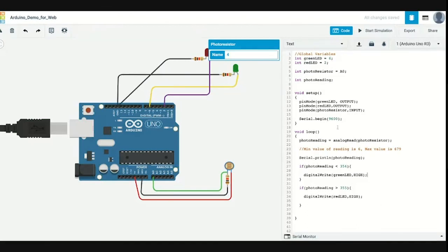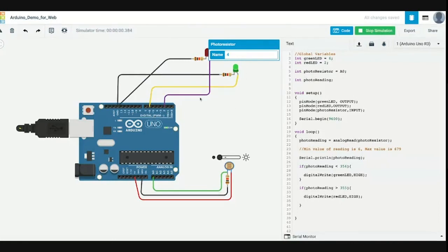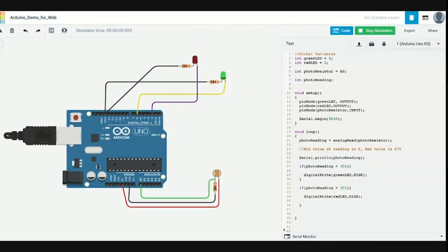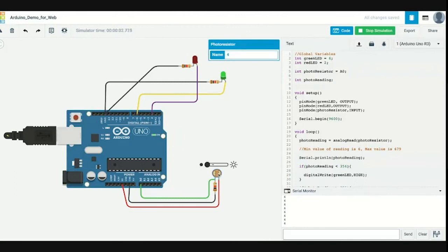But now we'll just run the simulation, and we'll have to notice something about the behavior of our program. Let's open the serial monitor and take a look at what our sensor is doing. So we can monitor the serial monitor from the sensor reading and check how the LEDs are interacting. Let's try to trip that threshold at 354. By dragging it up until it increments to 354, eventually that red light should turn on. But notice how both lights remain on and stay on when the conditions have changed.